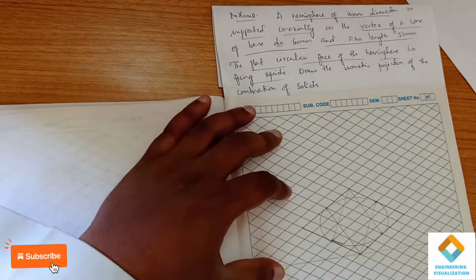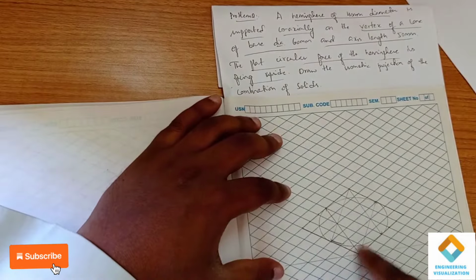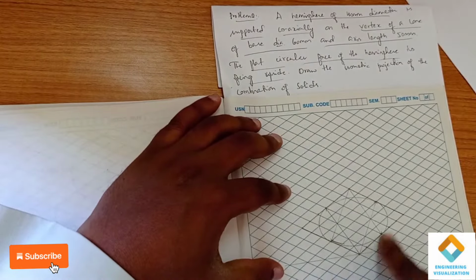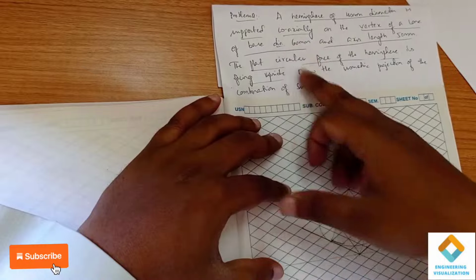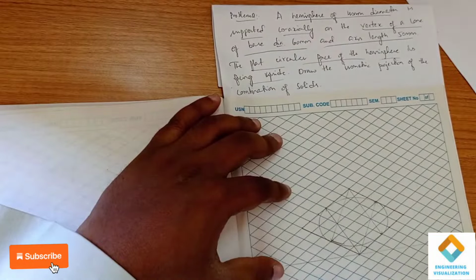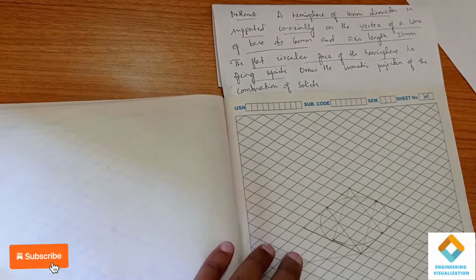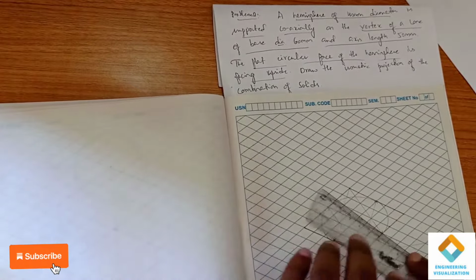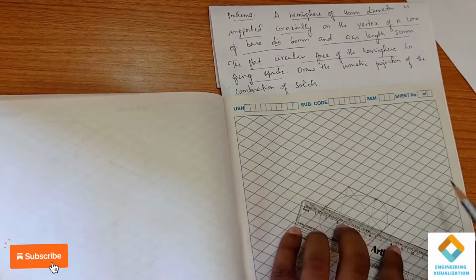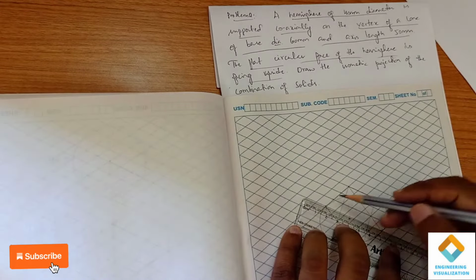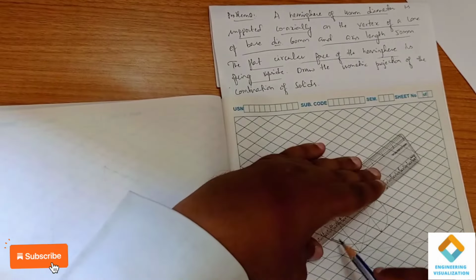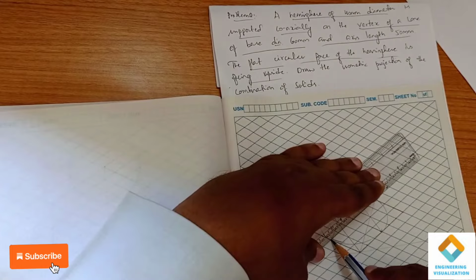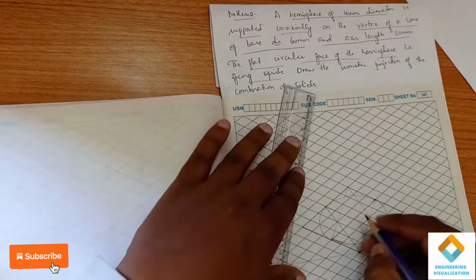Okay, so this is the base diameter. When it is constructed as an ellipse, it becomes the base part of the cone, the 60 mm diameter circle converted into an ellipse in the ISO. Now we have to find the center. We have an axis length, right? So the center of the box here, like this. This is the center of the box.